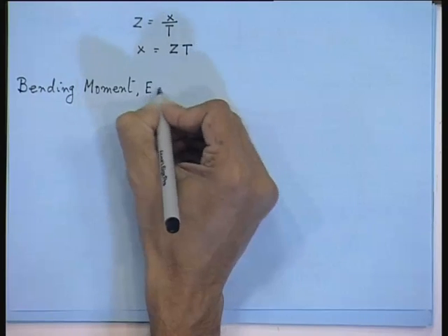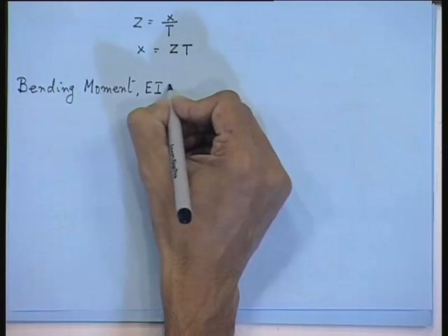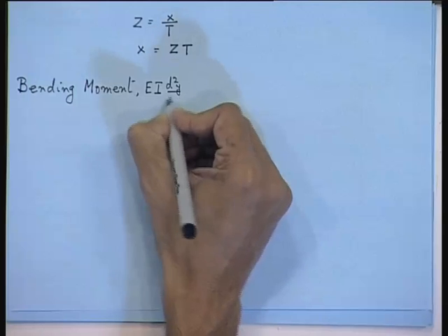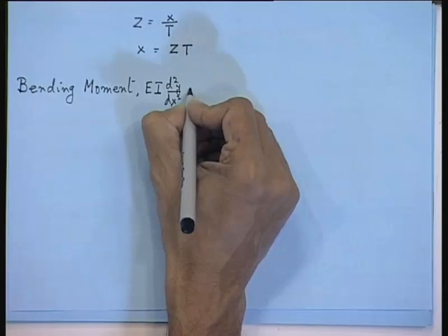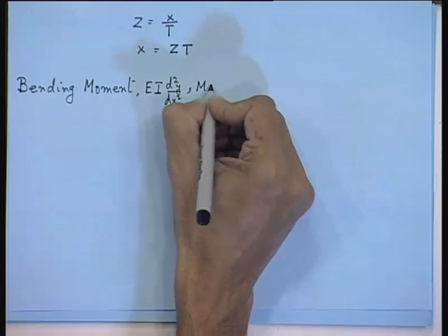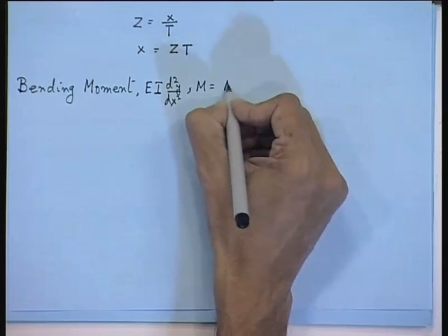The pile has been taken as a vertical beam and it is being applied with a point load on the pile head. So, what is the bending moment equation? You remember all this. EI d square y by dx square. So, you correct the constant terms. Now, bending moment is also of two parts, MA plus MB.